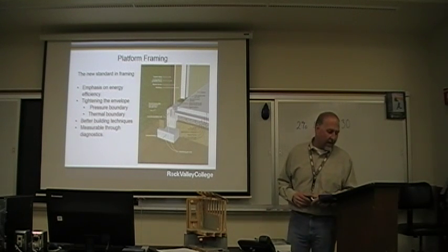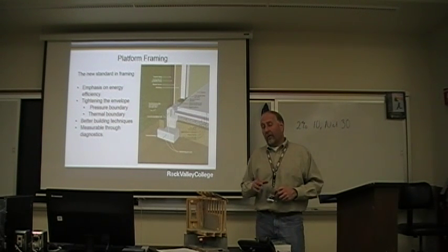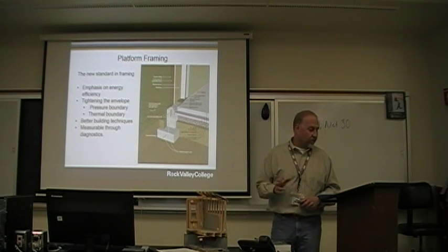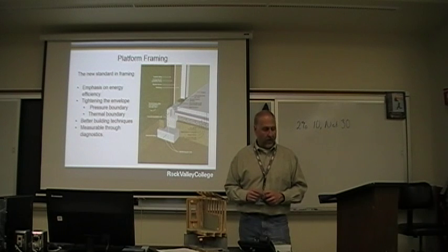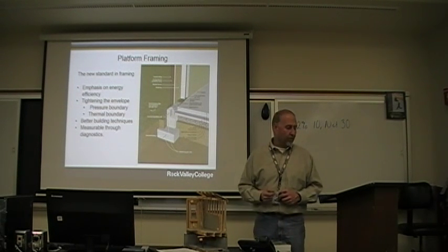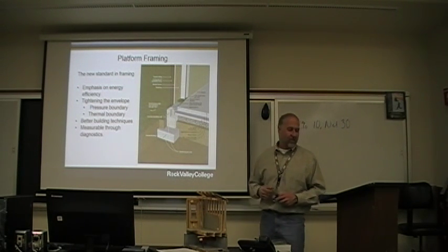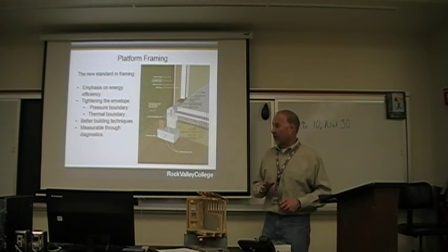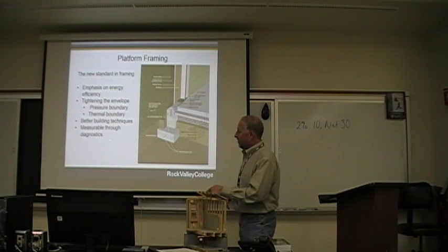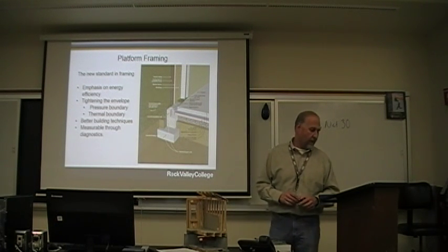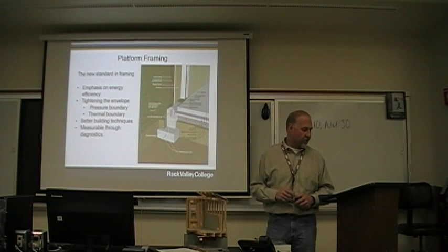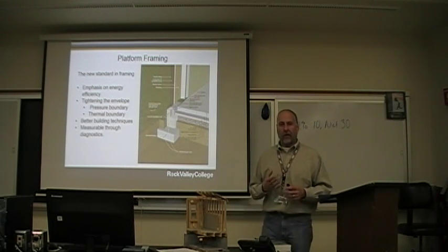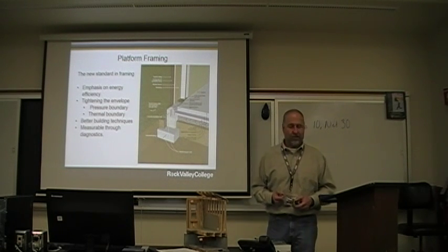Okay. Better building techniques, measurable through diagnostics. When I talk about that, I'm talking about what the standard is now, we're incorporating the International Energy Conservation Code. Most have adopted 2012. Okay, this code is focused on simulation-based compliance. So the code is measured here again through diagnostics. All right, the International Energy Conservation Code has a lot of similarities to the ASHRAE code.